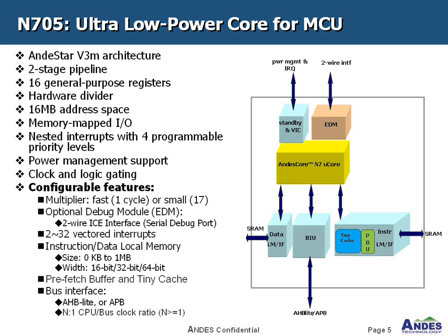N7 is a low power design. Users can use the standby instruction to put N7 into sleep mode. The other important feature is that N7 is configurable. Users can trade off between performance and area by choosing which multiplier to use. The fast multiplier needs only 1 cycle latency. The small multiplier needs 70 cycle latency, but it has a small area.